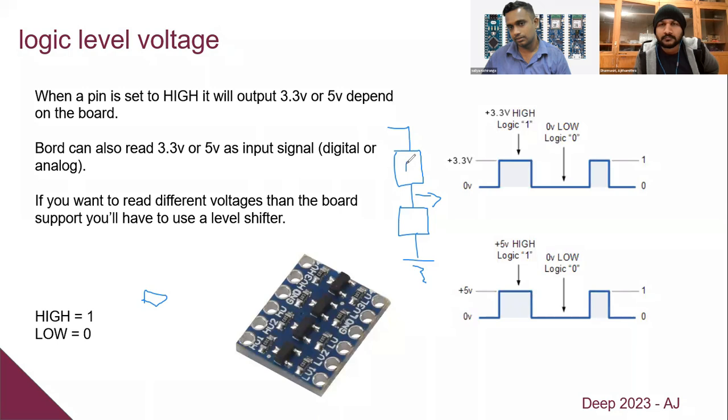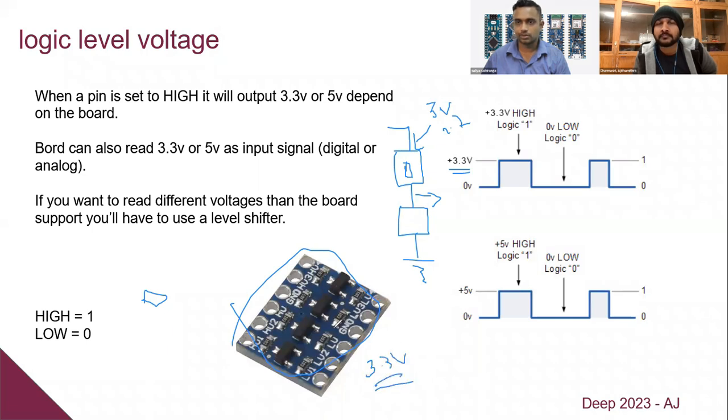The resistors you buy from the store have a tolerance, right? That tolerance means that you can't just have 3.3 volts. Maybe they differ, like 3 volts, maybe 2.7. They depend on the resistors, right? In these ones, they don't vary like that. If they say its output is 3.3, then you will get 3.3. This is reliable, not like this. It's okay to use at some points, but this is the recommended way.